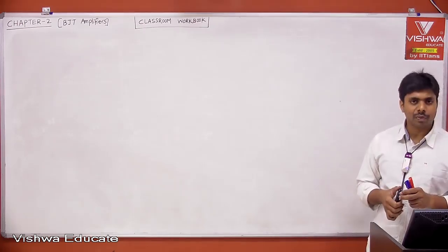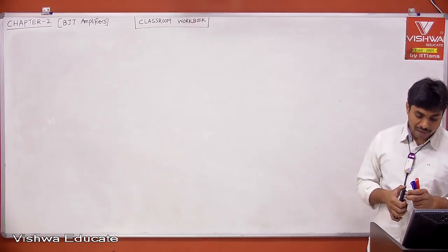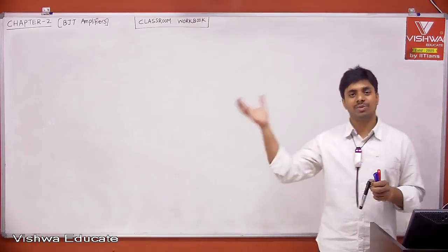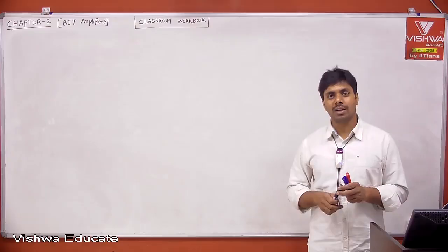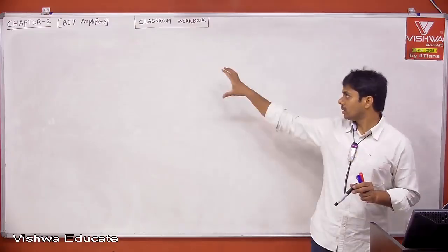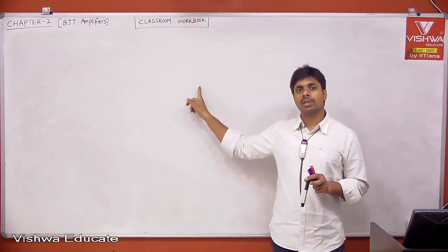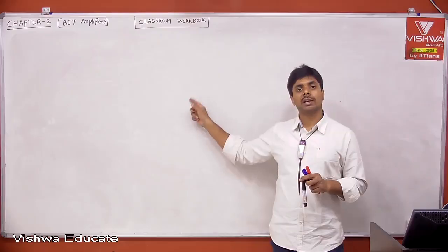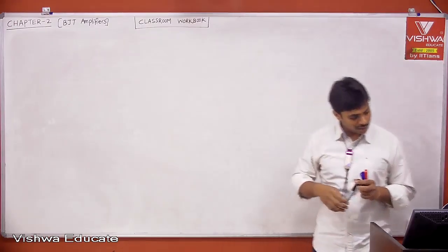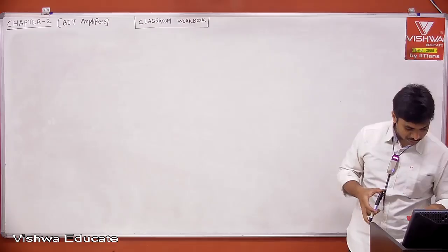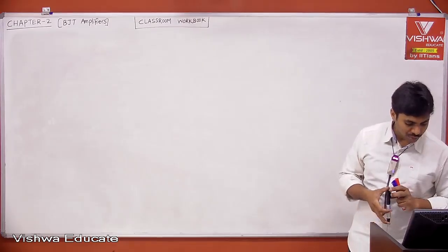We have seen, right? If the emitter resistance is not bypassed, it means CE is removed. If capacitor CE is removed, we already had seen this, right? If CE is removed, then surely your voltage gain will decrease because of negative feedback, and your input impedance will increase, right? Therefore, what is the answer? Reduce the voltage gain and increase the input impedance.